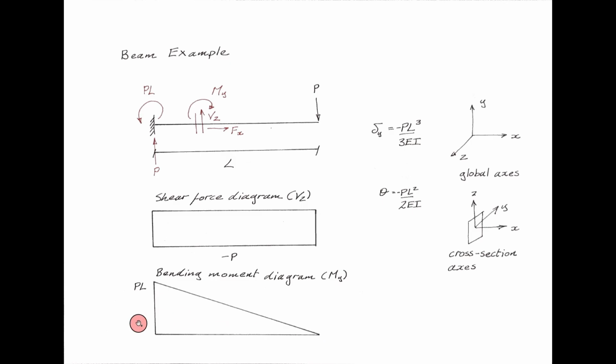The final thing to mention about bending moment diagrams: although obviously there are different conventions out there, generally I will always treat tension or the tension side as positive, so the bending moment diagram will appear on the side of the beam under tension. So in this case, what we're saying is that the top of the beam is under tension. Having outlined the problem, I'll pause and then we'll come back with a Grasshopper canvas open.